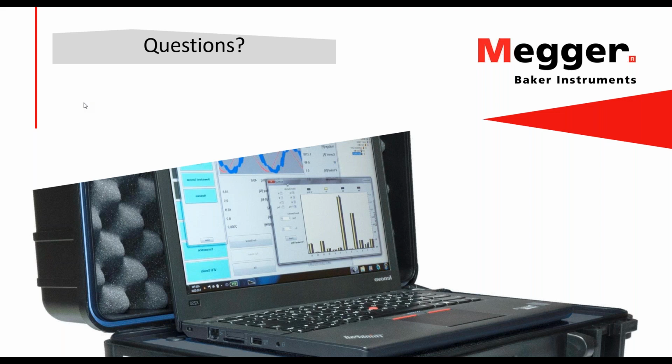Or is my plant 40 years old and I'm trying to keep old motors running, or I really have no idea what I got? If I'm in that situation, I have no idea what I've got out there, and I've got old motors, old plant, then I probably would go for static testing first. That way I can assess the state of the motors that I have, and do some work as I identify motors that are weak, that are less than reliable, and replace those. I would use static testing in that situation.